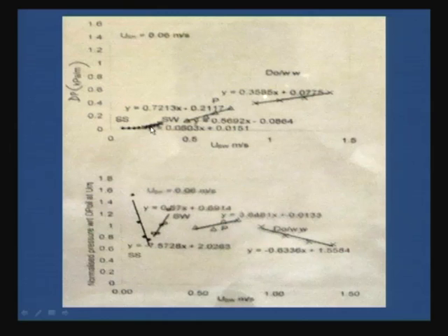Okay. So, under that condition, we use the pressure gradient or the pressure drop technique. We found that, if you observe, this is the stratified smooth pressure gradient, and then this is the stratified wavy, then this is the plug, this is the dispersed. So, we got quite different slopes or quite different curves for different flow patterns.